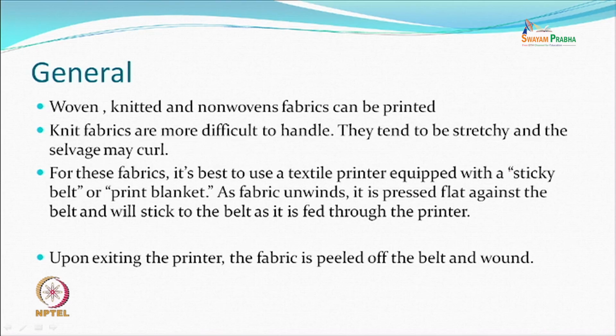Knitted fabrics invariably have stretchability, so one has to take extra care while printing. One of the cares is that you have a sticky surface: you paste the fabric on a blanket or a belt before printing, and after printing you peel it off from the belt and wind it.